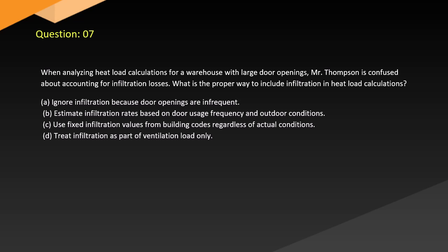A. Ignore infiltration because door openings are infrequent. B. Estimate infiltration rates based on door usage frequency and outdoor conditions. C. Use fixed infiltration values from building codes regardless of actual conditions. D. Treat infiltration as part of ventilation load only.